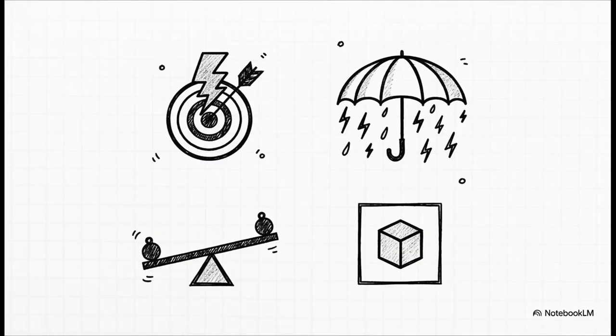And that gives the active filter some literal superpowers. It acts like a high-tech scalpel. Because it's fully dynamic, it adapts instantly to load changes with a blazing fast response time of under 1 to 2 milliseconds. Plus, it's not limited to just the 5th or 7th order. It provides wide spectrum filtering all the way up to the 50th order.